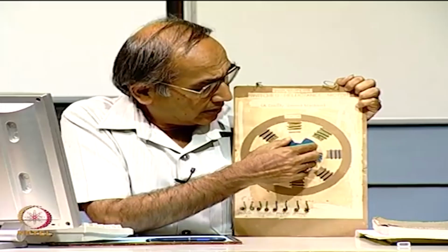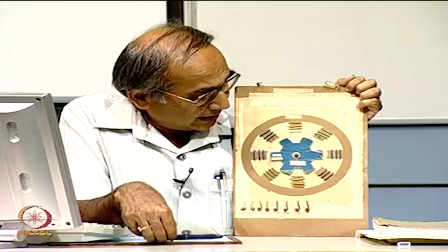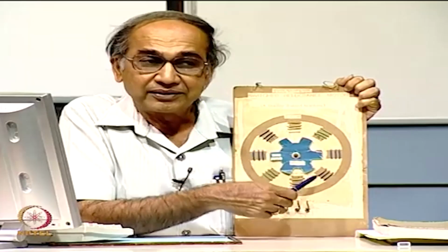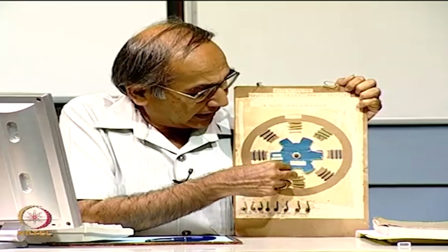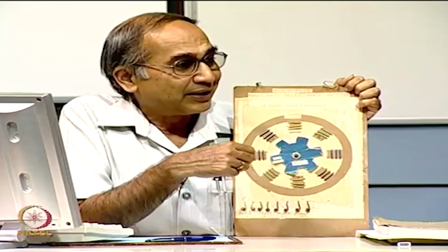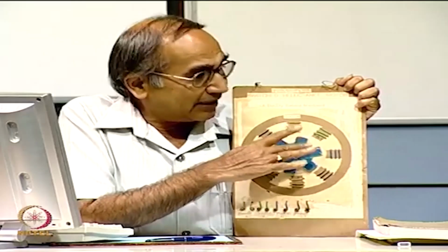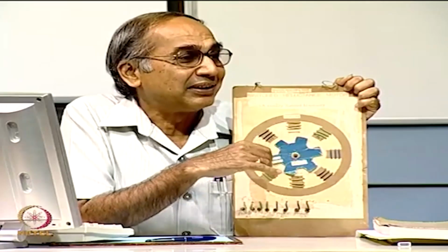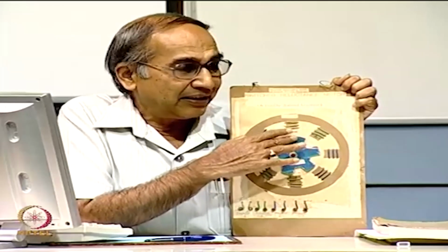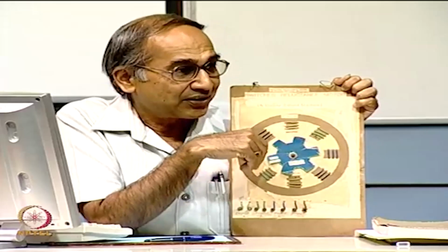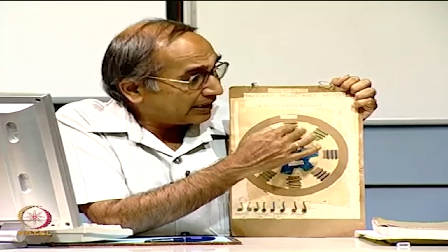It will move like this, and then I excite the black coil, it will again move like this. The angle of movement is like a Vernier principle in a way, it is the differential angle between this axis and this axis, it will not move by the exact angle.